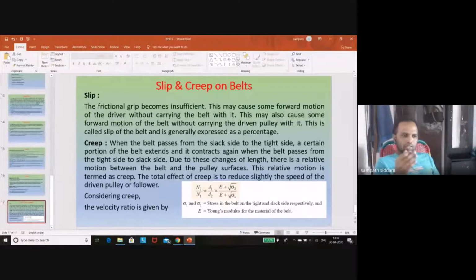So your slip gets negative when you have a direct contact that allows the water to lift and flow continuously. That's the case of your reciprocating pump. Usually the slip cannot be zero, it will be either positive or negative. In most practical cases it will be positive slip. In very rare cases you get a negative slip, but negative slip is a good sign for your reciprocating pumps.